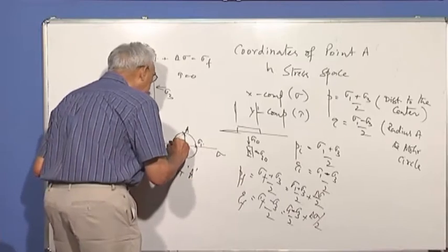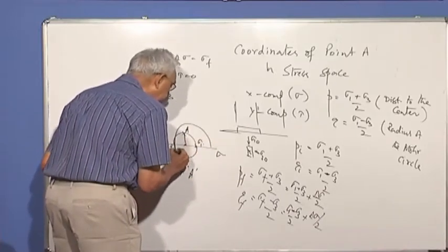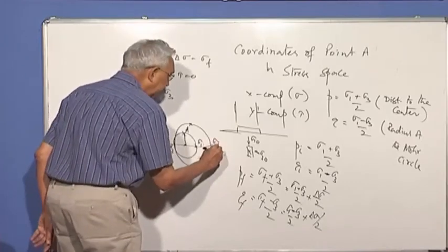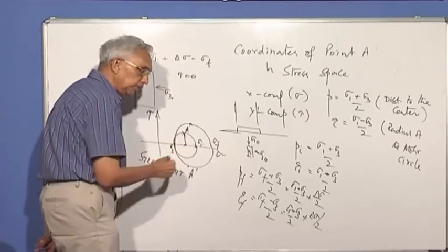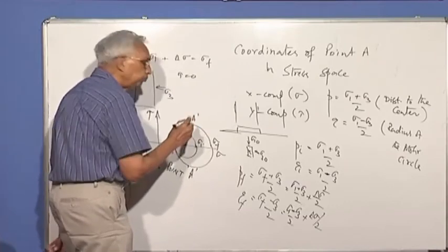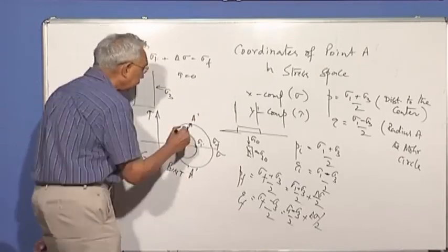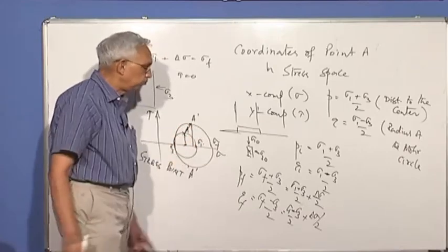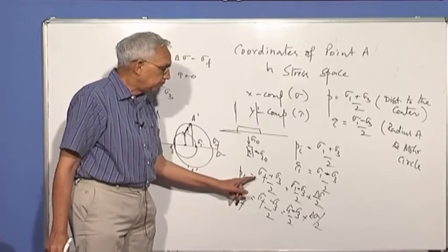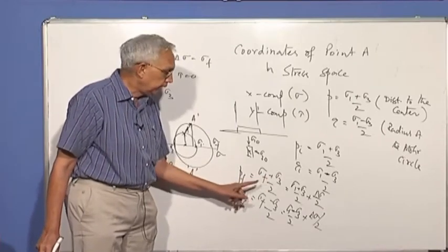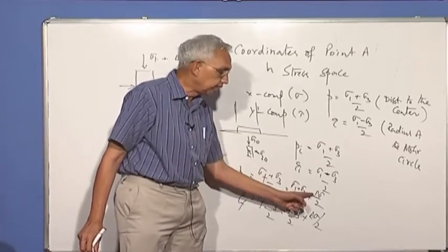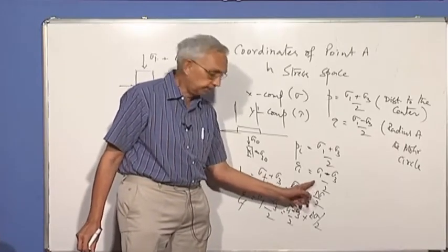So basically what you have got is a different Mohr circle and the point goes up because this is sigma final. Now instead of drawing so many circles, what we say is, why not simply show point A going to A prime. What are the coordinates of A prime? PF and QF. How did you get PF? Sigma F plus sigma 3 by 2, which is the same as sigma 1 plus sigma 3 by 2 plus half of the increase in the vertical stress.